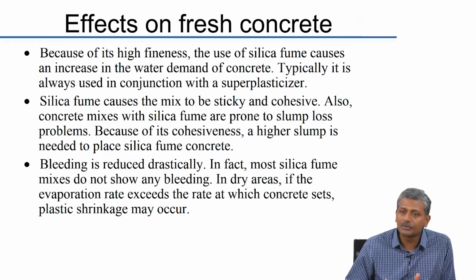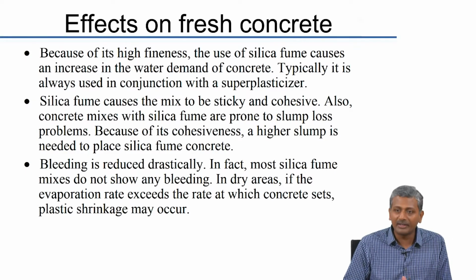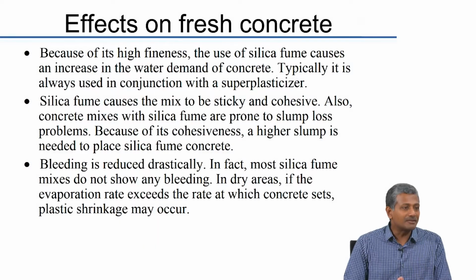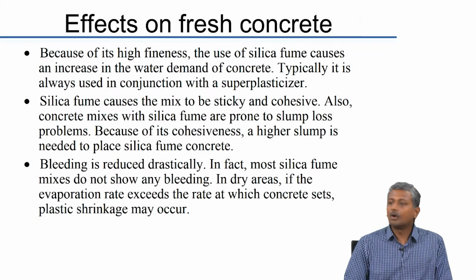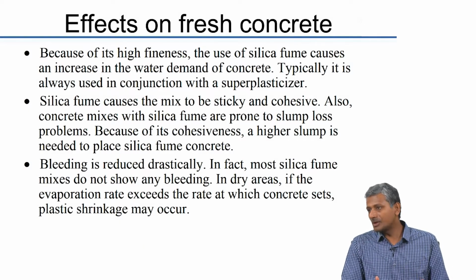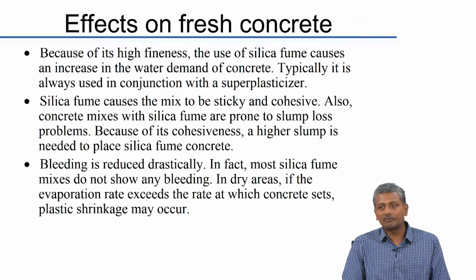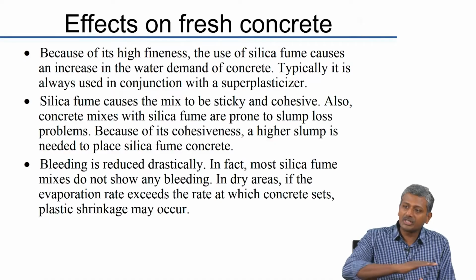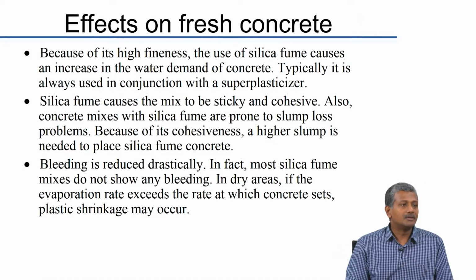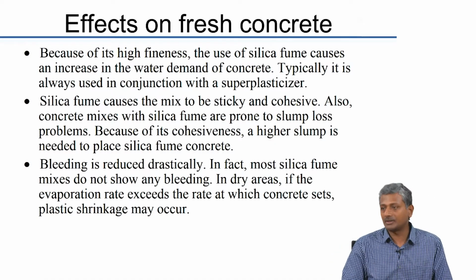Okay. Now, of course, because of silica fume being so fine, there is no question of any bleeding from silica fume mixes. Now, bleeding is obviously a negative thing to happen in concrete, but there is one positive attribute to a little bit of bleeding from the concrete, is that it provides a sheen on the surface of your concrete that protects the internal water from evaporating.